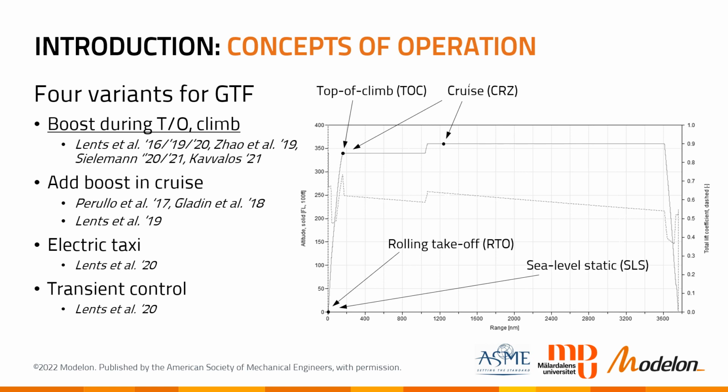And there is some hope that it becomes possible to downsize the thermodynamic core, what we call the gas generator in the previous slide, and then get some improvements for those turbofans. And for turbofans, that's the most widely discussed concept of operations. Second, one could also apply electric boost during cruise, and some people see benefits in this for turbofans, but there is also a lot of skepticism because of the weight of the required batteries.